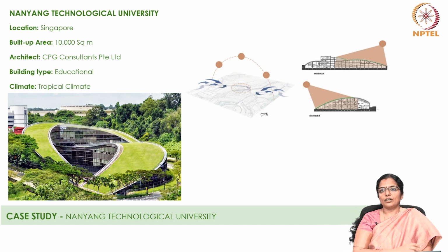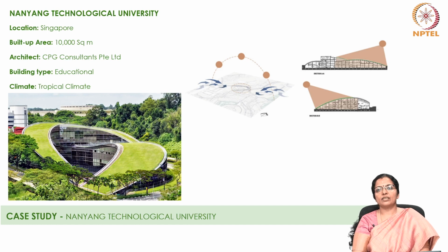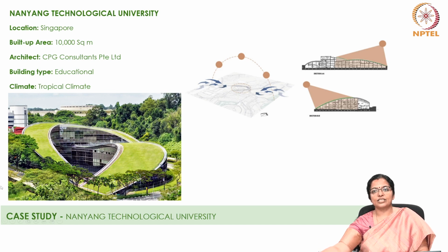The sloping green roof has helped to minimize the west openings and shades the rest of the building. On top of the two curves which interlock each other is a very dense grass turf which forms a green roof. Apart from the way it looks, which is extremely aesthetically appealing, the green roof helps to absorb the intense solar radiation and therefore reduces the thermal heat gain inside the building. It is more or less like a natural insulation.